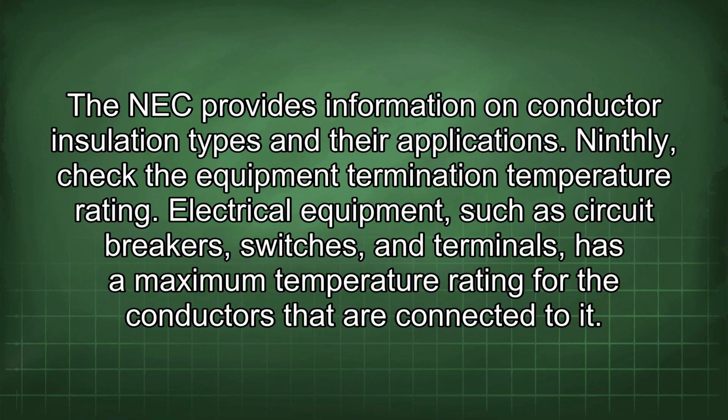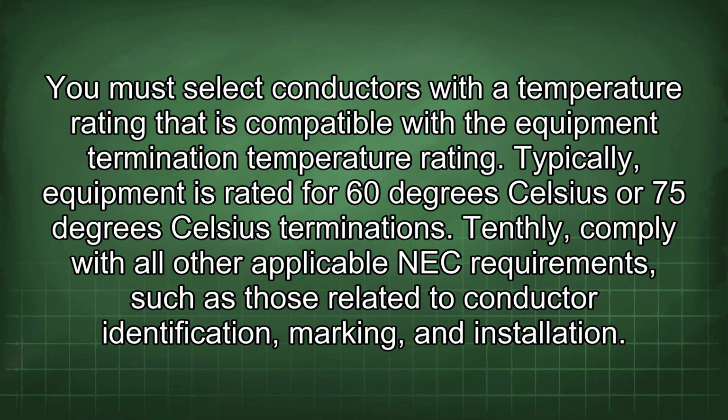Ninthly, check the equipment termination temperature rating. Electrical equipment, such as circuit breakers, switches, and terminals, has a maximum temperature rating for the conductors that are connected to it. You must select conductors with a temperature rating that is compatible with the equipment termination temperature rating. Typically, equipment is rated for 60 degrees Celsius or 75 degrees Celsius terminations.